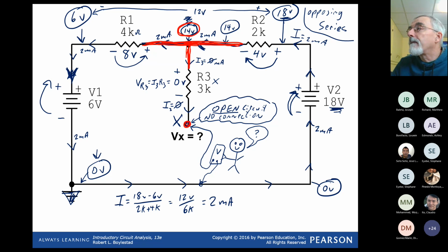X is down here. We do indeed cross a component. If we cross a component, we're traveling through the circuit. We start at the voltage that we're at, and we must drop or go up the amount of voltage that we encounter as we go through a component.